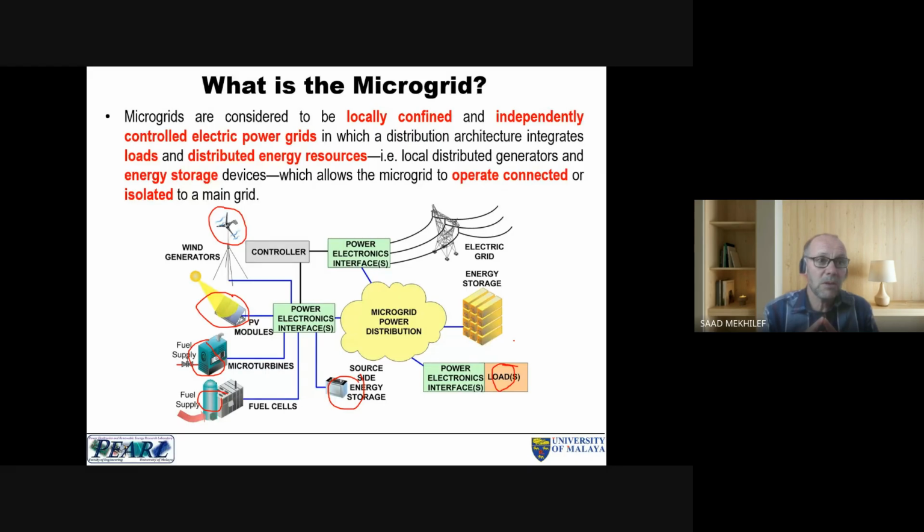I'm sure maybe some of you have used the HOMER software. This HOMER software will help you do this techno-economic analysis, and also do the sensitivity analysis. Sensitivity analysis is where, for example, what will happen if I increase my solar? What will happen if I increase my battery storage? What will be the cost? What is the renewable energy factor? We call it sensitivity analysis, because it will give us the idea of what will be the best design options that you should have.